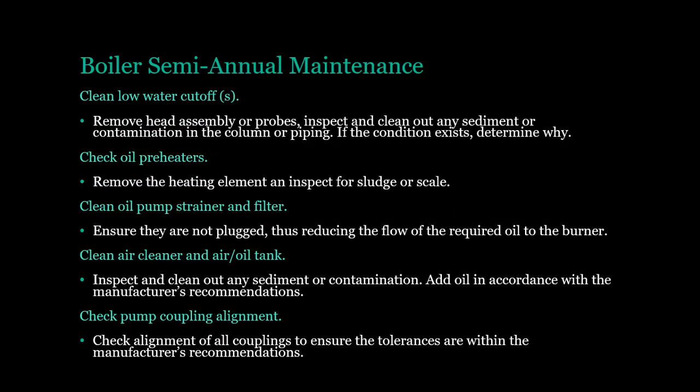Boiler semi-annual maintenance. Clean low water cutoffs. Remove head assembly or probes, inspect and clean out any sediment or contamination in the column or piping. If the condition exists, determine why. Check oil preheaters. Remove the heating element and inspect for sludge or scale.